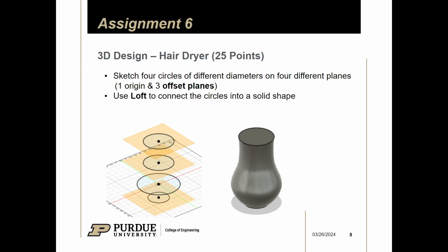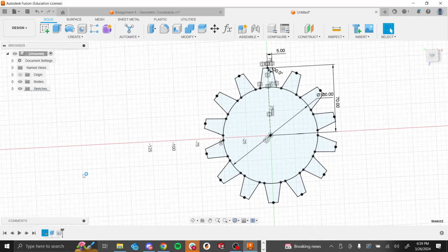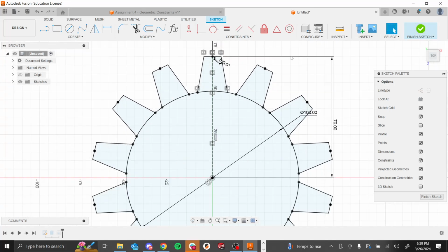Yeah. So you have to make sure you're in your sketch to create the mirror. So you can mirror objects, but you can also mirror your sketch. Down here on your timeline, there's your sketch, and you have to make sure you're editing it. A good way to know that you're editing a sketch is if you see this green check mark. Now if you create your mirror over here, it should pop up like this, and then you select your lines, and then select the mirror line.